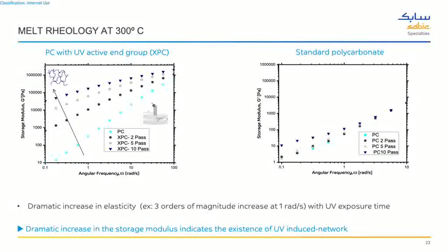And then if you cross-link it, you can see those cross-linkable moieties increase the modulus to some level and extend the temperature a little bit more. So for example here, this is the actual flame plaques for the 5VB test. You can see that when you have a material with good cross-linkable moieties and good cross-link density, it does resist the flame, creating only a small hole, whereas the polycarbonate forms a big hole.